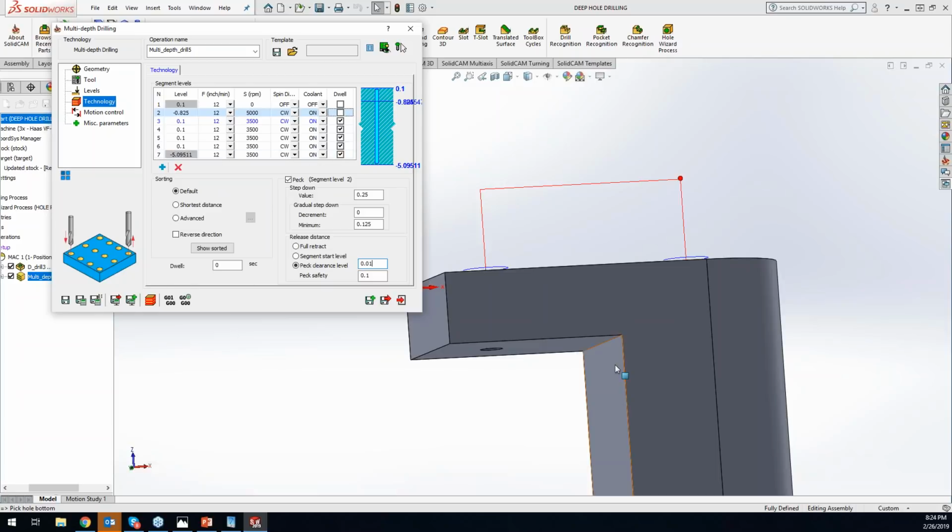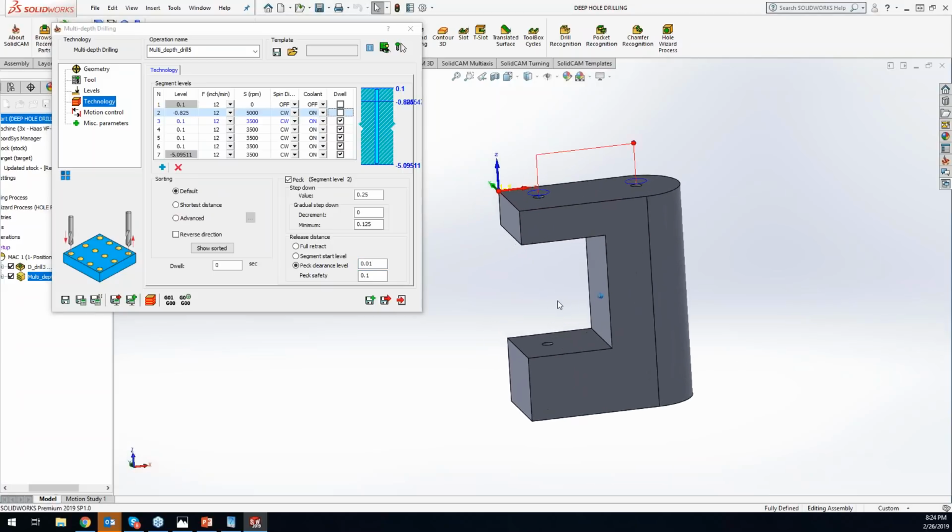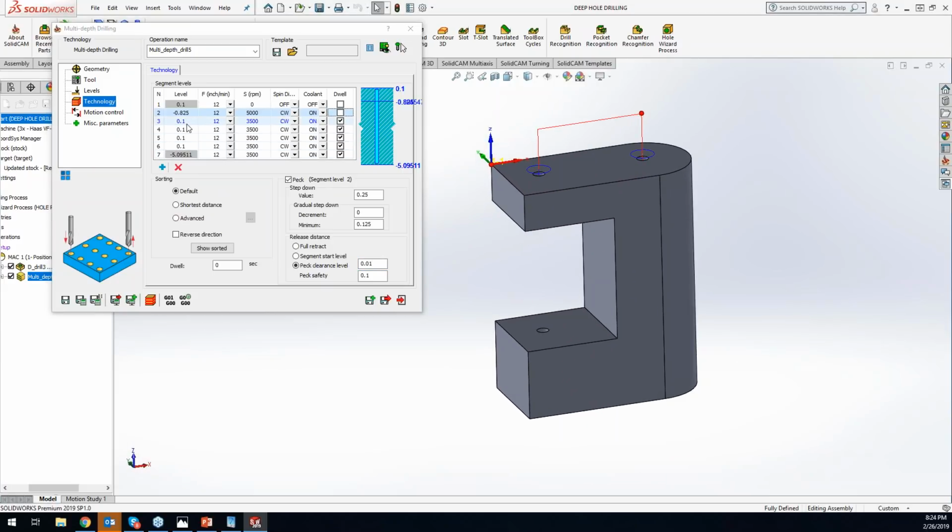Okay. So now, from right here to here is just dead space. So I really don't need to do any custom drilling or anything like that. Let me get this rotated around here. And so now for my next distance, like I said, highlight your field right here. So right to the 3.4998, we'll just round this off to 3.4. I'll have my spindle turned off.